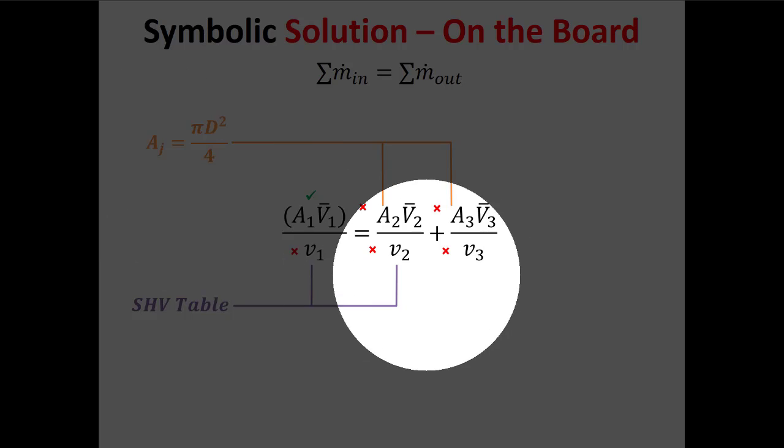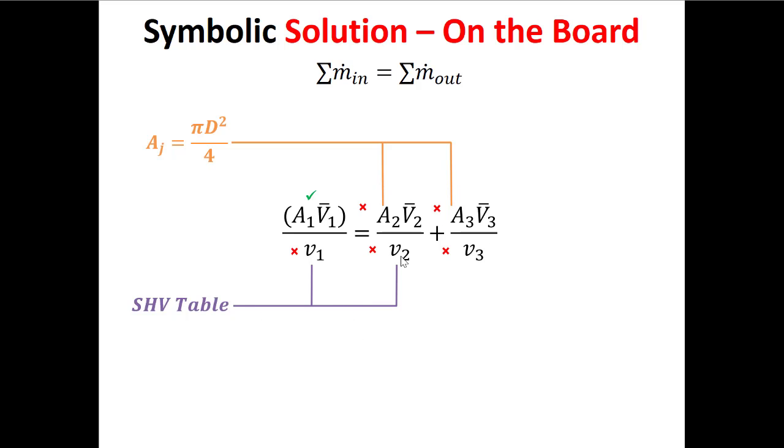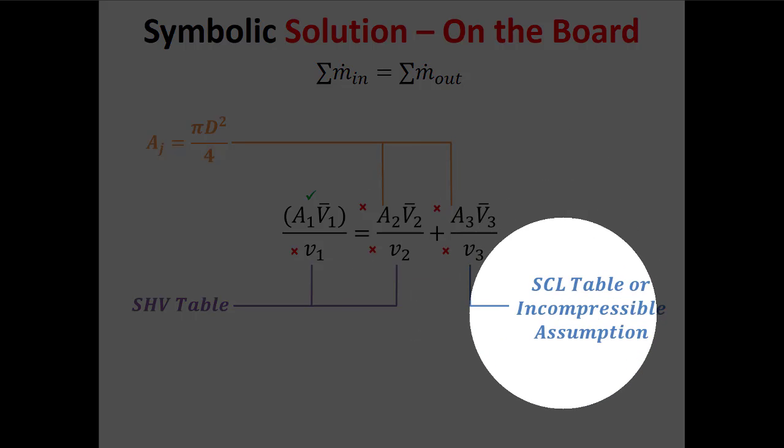At state 2, they told me the temperature and the pressure. So I'm hoping that those are still independent properties, which would be true if it was superheated vapor. State 3, they told me that the fluid had a quality. Anytime there's quality and you're talking about fluid, it means there's some kind of mixture of saturated liquid and saturated vapor. So I know here I'm going to look under the vapor dome.